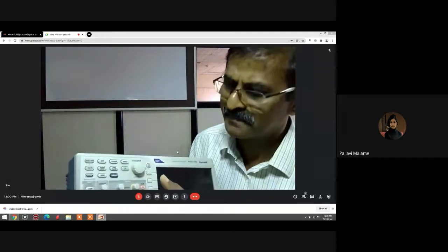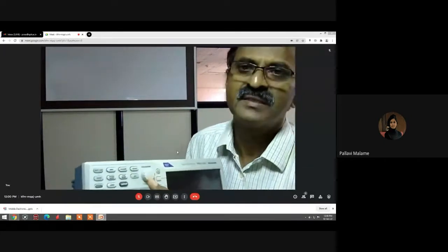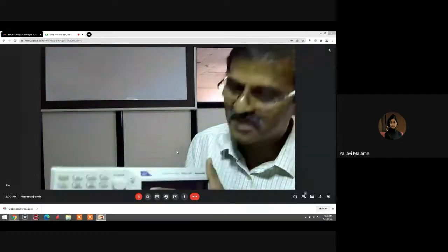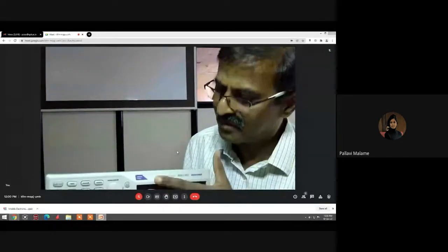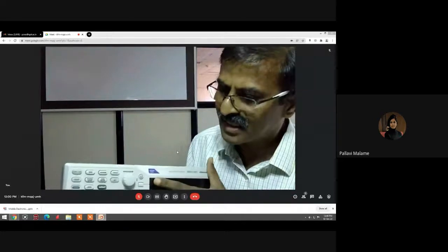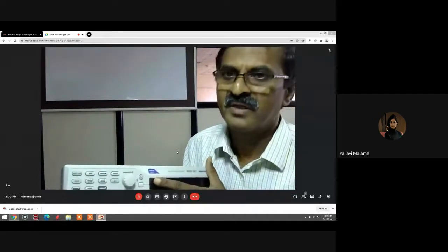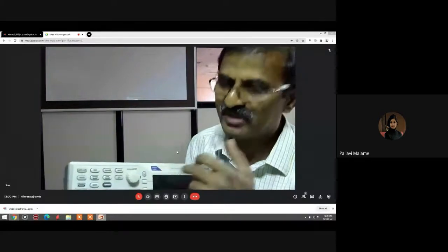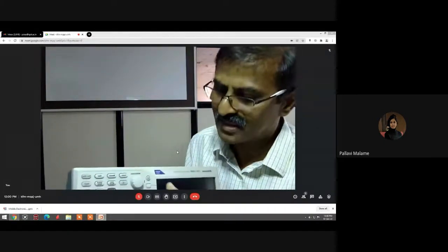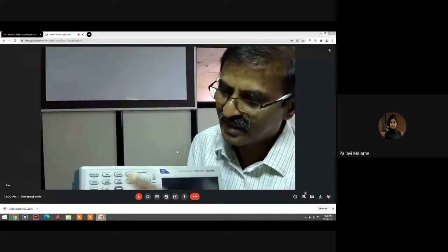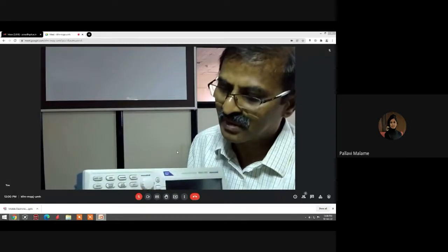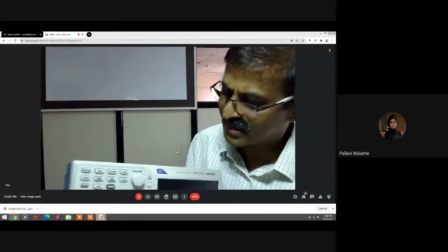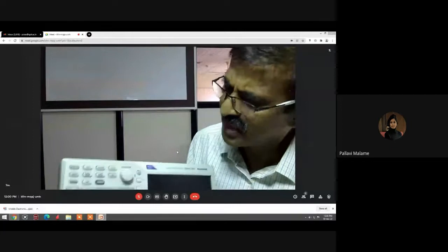of the signals. There is a trigger signal, where if you want to display a stable waveform on screen, the signal should be triggered. That means the sweep generator should be triggered with reference to what? This X or Y, so that has to be decided. What is that magnitude of the input that you have to select from the trigger signal. Similarly, you have other options.